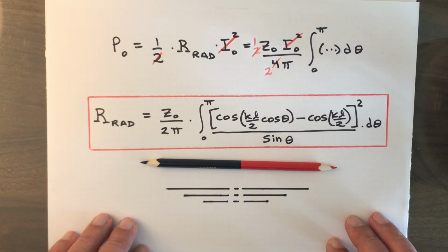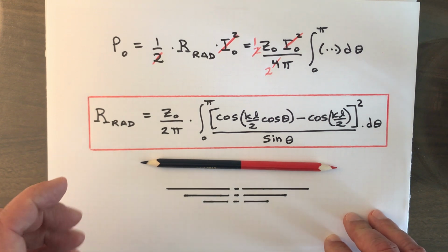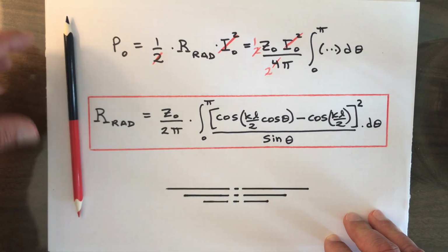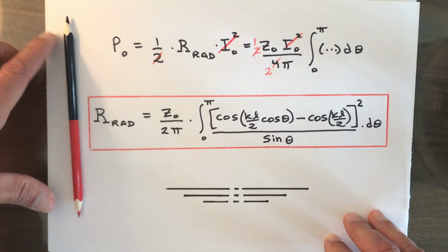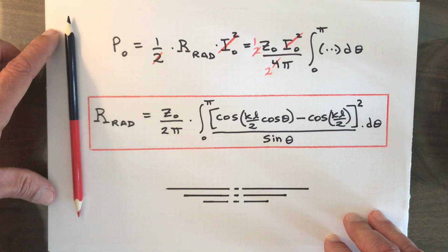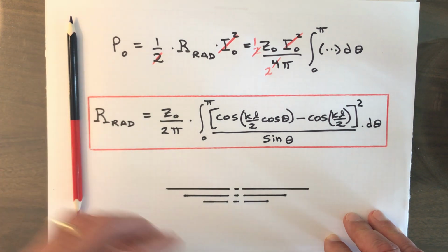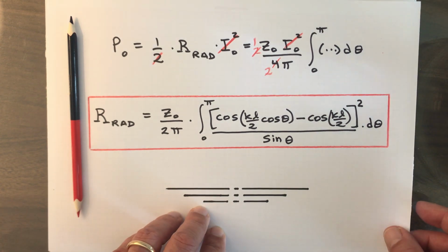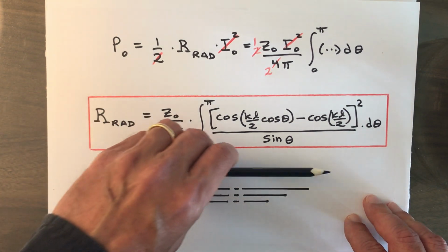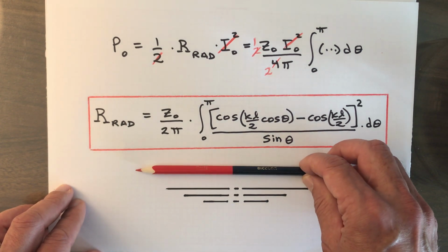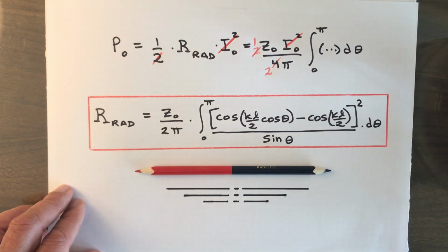And again, this is for a finite dipole. Finite dipole being applicable for an antenna length that is between 1/10 of the wavelength of interest to maybe even 3 times the wavelength of interest. So that concludes the presentation, and that concludes the series so far, arriving at the finite dipole derivation.